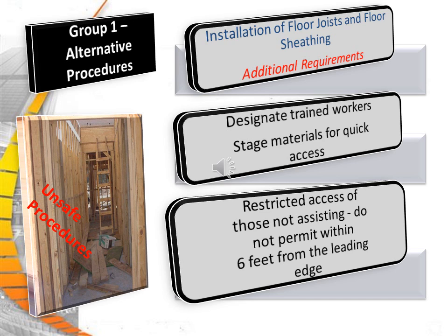Additional requirements call for trained workers, stage materials with quick access, and a restricted access zone for those not assisting. Do not permit anyone within 6 feet of the leading edge.